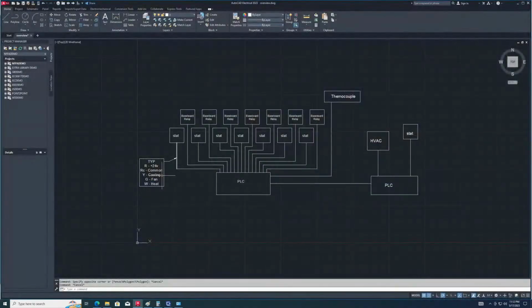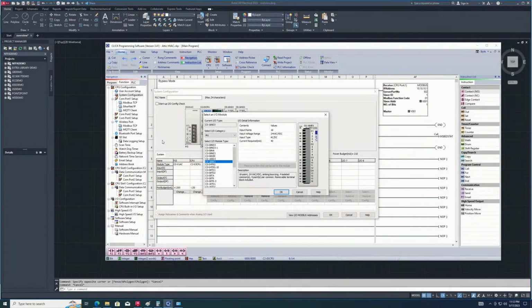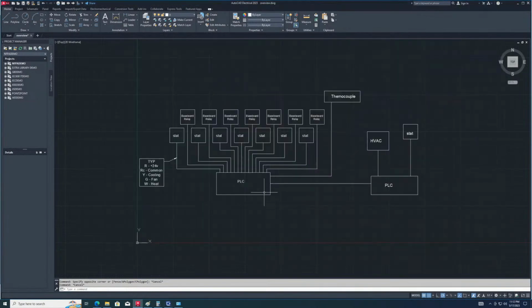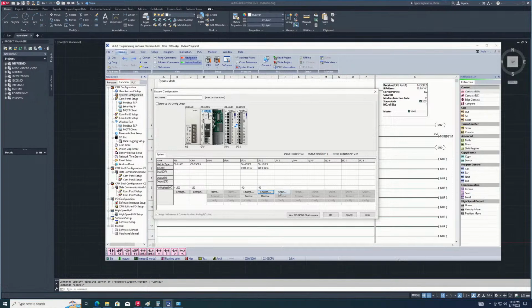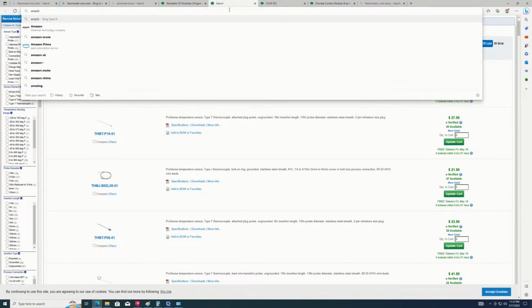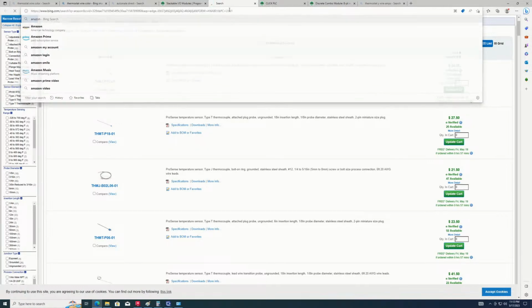Yeah. So if we're running this, we need 1, 2, 3, 4. 4 times 7 is 28. So we need 28 discrete inputs. If we have 16 inputs, we're gonna need 2 of these for all the thermostats. We need an output controller for the relay. Actually, we need to look up that relay on Amazon. I don't know if I'm going with the Honeywell relay.